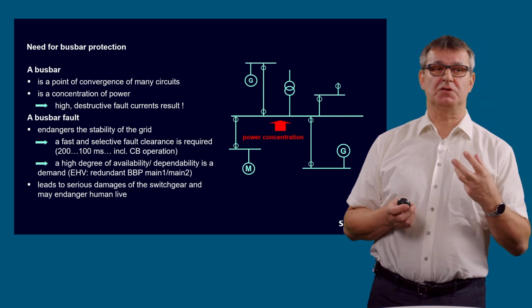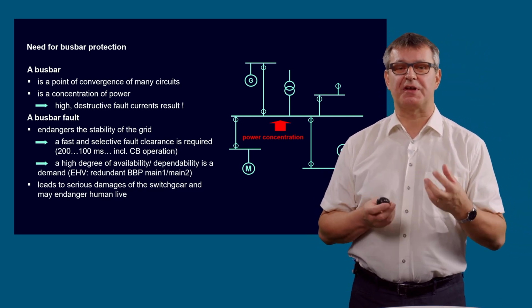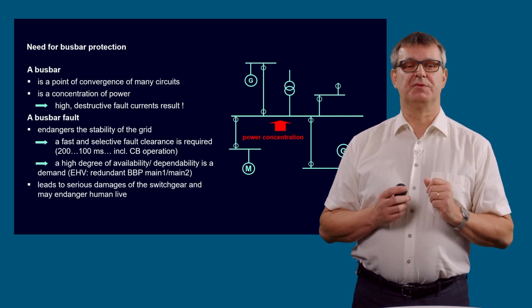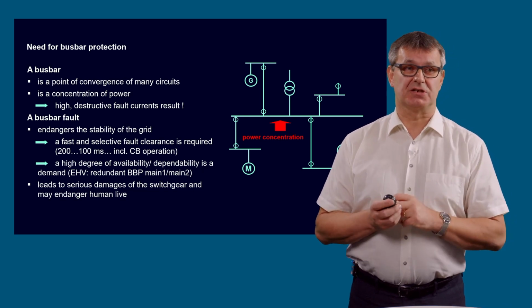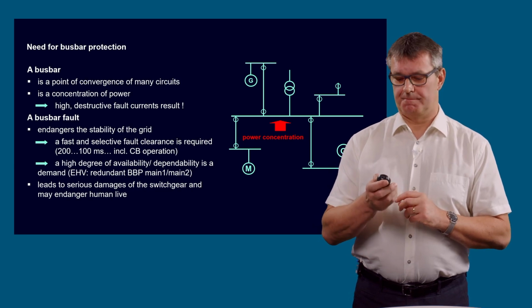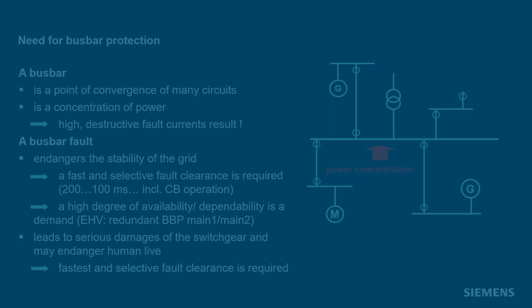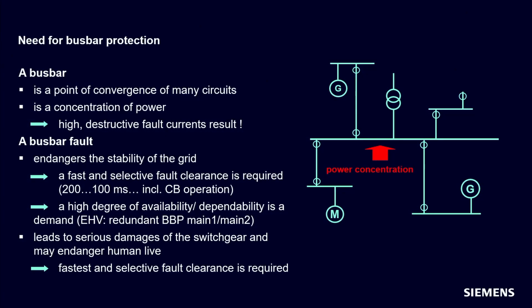And a busbar fault, because it's very destructive, can lead to very serious damage to the switchgears and may also endanger human life. Therefore, once again, a very fast and selective fault clearance by busbar protection is necessary.